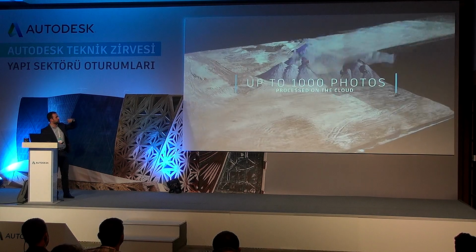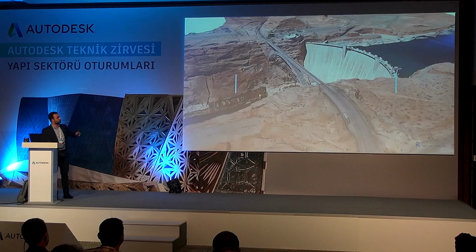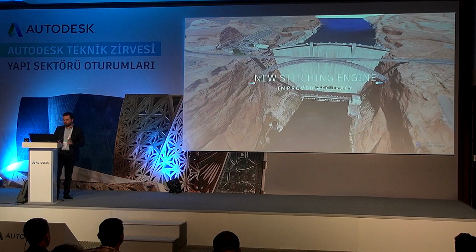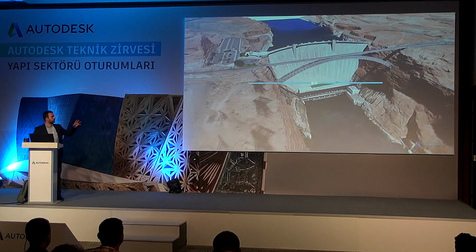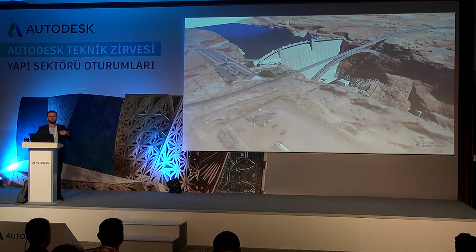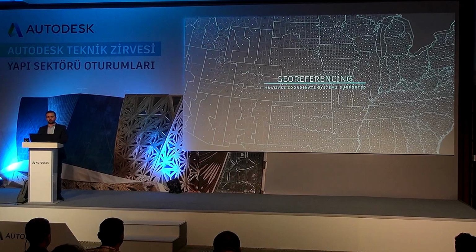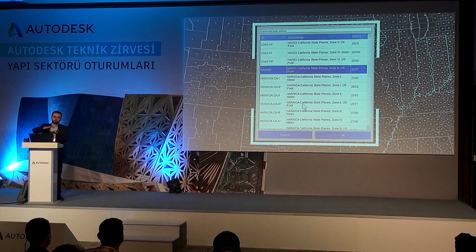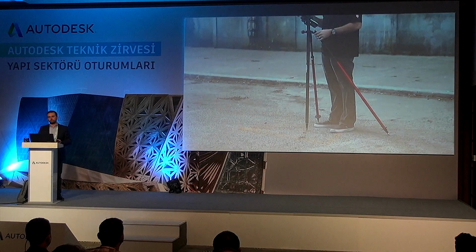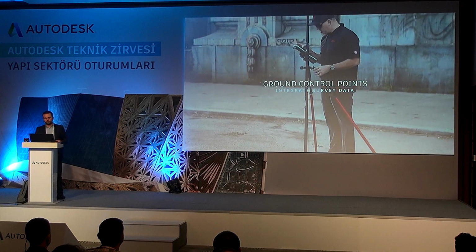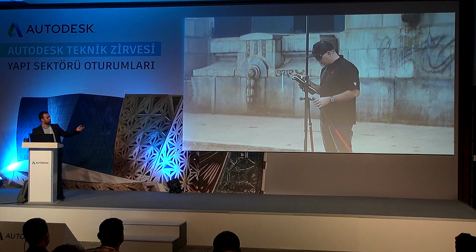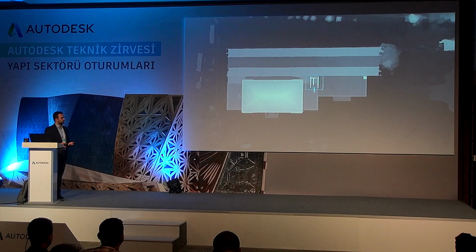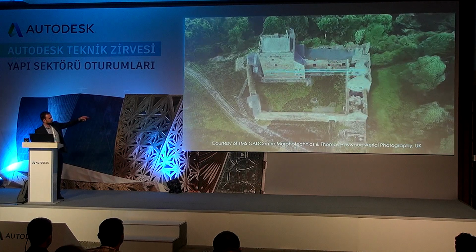They're sent to the cloud, and then within a few hours to 1 day, you receive a 3D model of whatever you've captured on site. Now, the 3D model is good if you take the picture in the right manner. So there are many requirements on how to position the camera, what is the percentage overlap, the weather conditions, etc., etc. But once you get that model, you're able to georeference it, put the X, Y, and Z coordinates, because what you actually get is a 3D mesh.